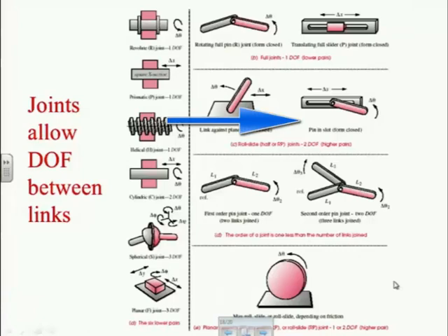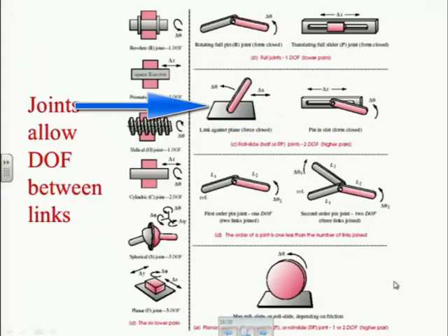What else have we got here? Pin and slot. That has the same kinematic characteristic as this link on the tabletop, except that I now can't pull them apart. So the one I have in my hand, the link sliding on the tabletop, which I can also rotate, thus it's 2 degrees of freedom, I refer to that as a force-closed joint. I have to push down on it to keep it together. Once it comes apart, the joint disappears. It doesn't exist anymore. Okay?